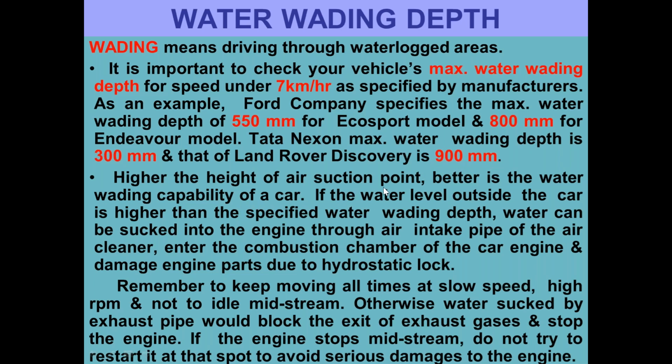The higher the air suction point, the better the water wading capability of a car. If the water level outside the car is higher than the specified water wading depth, water can be sucked into the engine through the air intake pipe of the air cleaner, enter the combustion chamber of the car engine, and damage engine parts due to hydrostatic lock.